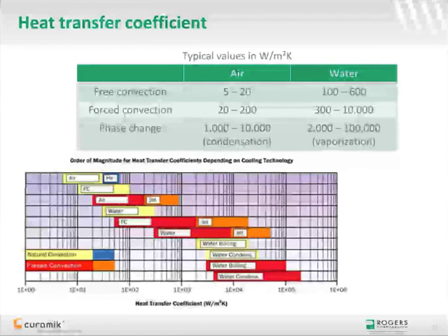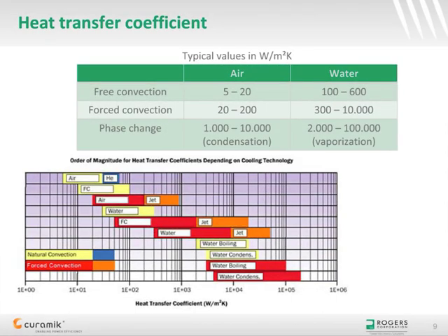The heat transfer coefficient is the ratio between the heat flux and the thermodynamic driving force for the flow of heat, in our case, the temperature difference. Typical values for heat transfer coefficient vary from very few up to many thousands watt per square meter Kelvin. As was shown before, for a given medium, forced convection is always better than free convection, but higher costs are associated with the required external source for fluid movement.